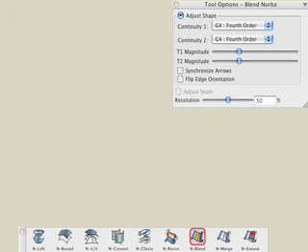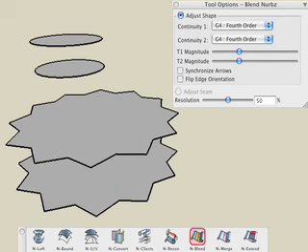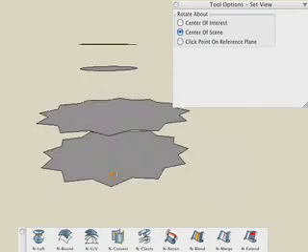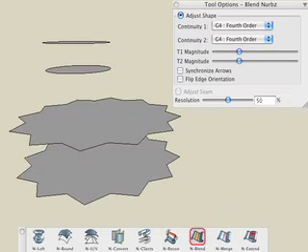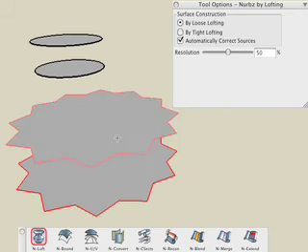The one parameter that we didn't look at yet is the Adjust Seam option, which is only available when blending is applied between the open edges of Nurbs surfaces that are closed in one direction. For example, we'll loft a couple of Nurbs surfaces using closed 2D shapes. On the bottom we have a couple of 2D star shapes, and we'll select the Loft tool, click on both of those, and we have a Nurbs surface on the bottom.